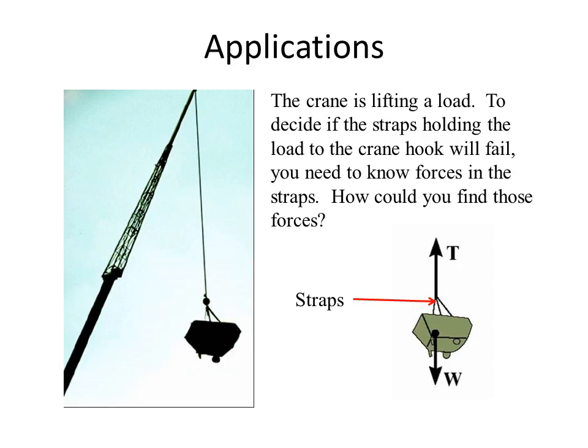Some examples of applications for these topics that we can look at the start will be an example such as this crane, which is lifting a load, but to decide whether or not the straps can support the weight, you need to look at the forces in each of the straps and find out how those forces compare to the strength of the straps. To complete that analysis, you'll need to be able to draw a free body diagram and determine each one of the forces in the straps.